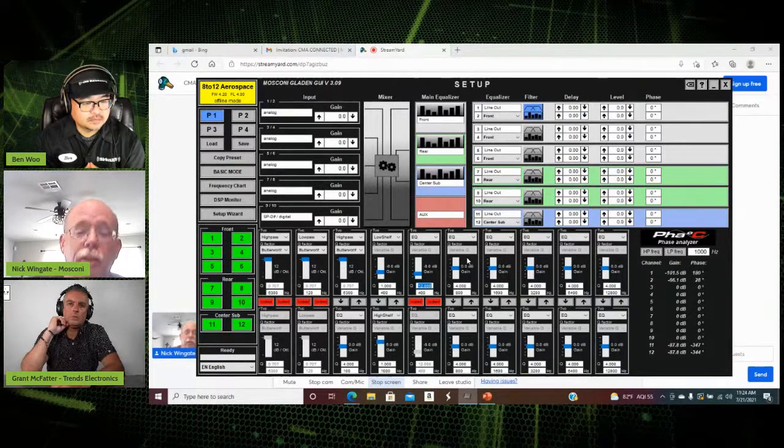You can literally get a flat line right here with this. With every driver. With every single one. Yes, you can do it. If you've got a rise in the mid-bass from, let's say, 200 hertz to 315 hertz, your crossover is 400, you've got a big problem here. This is where the wide Q comes into play.